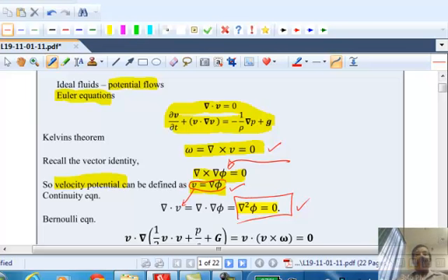Once, of course, we get the velocity profile through the definition, we can take the velocity profile and plug it in there. And we can calculate the pressure profile out. We need to get the velocity profile and pressure profile. Remember, these are the 4 variables, 3 velocity components and pressure. So we can get the pressure profile from the momentum equation.